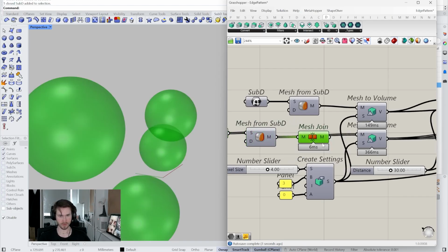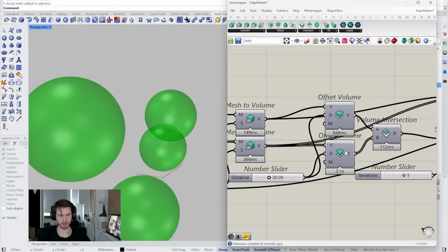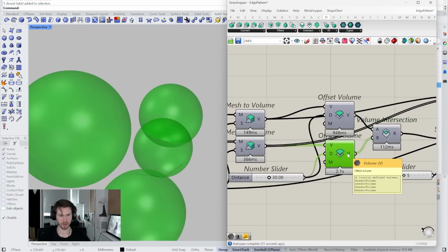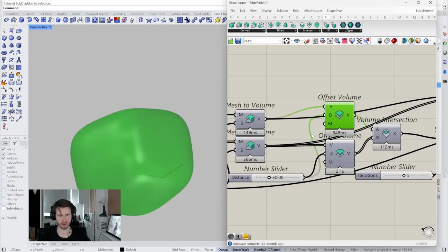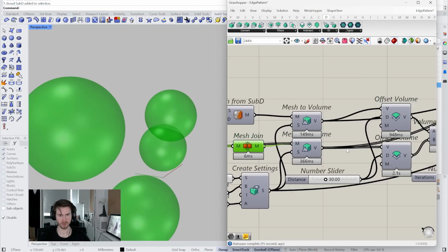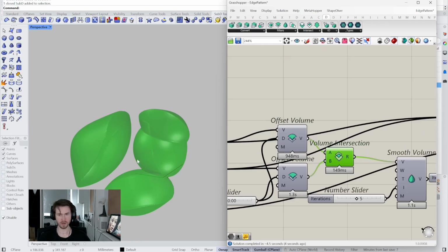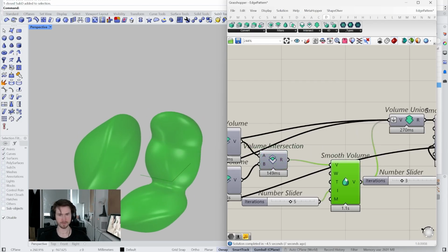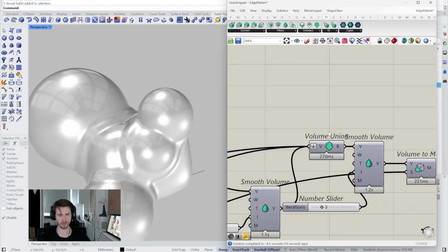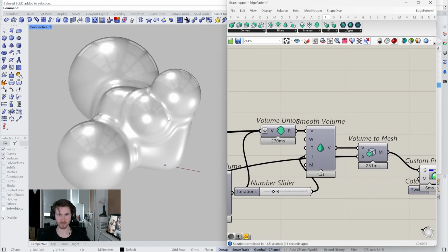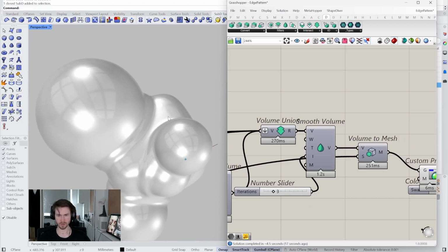So now these are all a single mesh, because right here with the intersection we're getting a bad result just because we have 4 separate volumes here compared to this one for the box. If we have them all together as a single mesh, that should solve that, because then it'll give us only one volume for all the spheres. So one volume there, do the intersection, get a much better result. Let's turn off this, and now we can see the intersections a lot better here. These 3 different ones, 4 different ones.